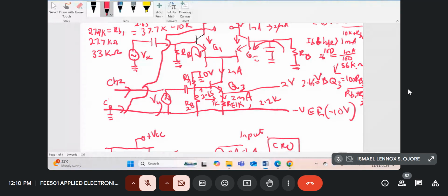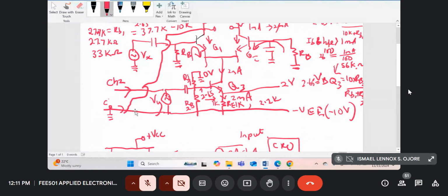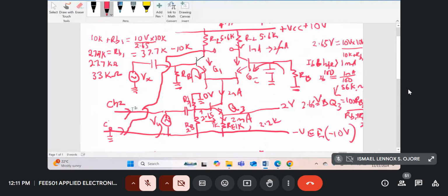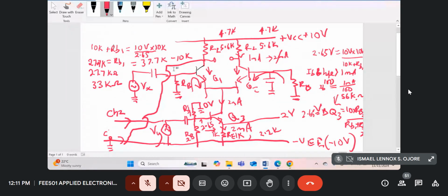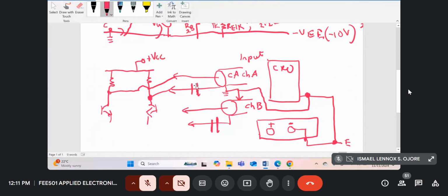I don't have a lot of time to explain it very clearly, but what I just want to say is you've got to be very careful, especially when you've got a three-way power supply like this. You always got to remember that the scope is designed like this. Channel A, the middle is live, the body is grounded. Channel B, the body is grounded. So if you're monitoring one signal from minus VEE and you put the body connected over here, this body of channel B is going to be grounding one of the inputs of channel A, because inside the scope those 2 points are connected. So the way to do away with that, you've got to isolate the grounds by using a capacitor in between. You've got to isolate the two.